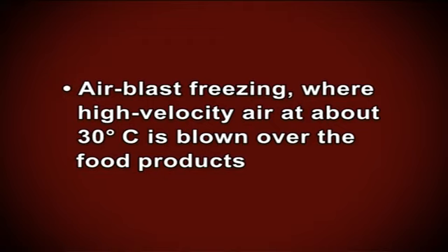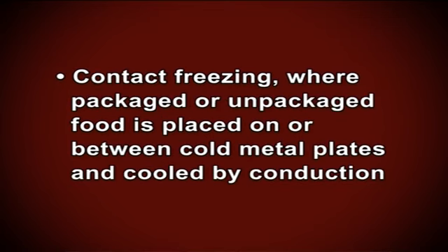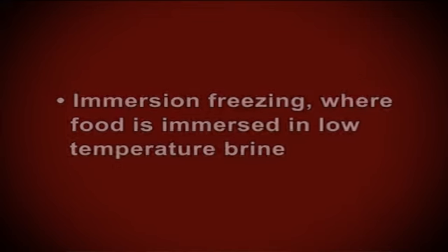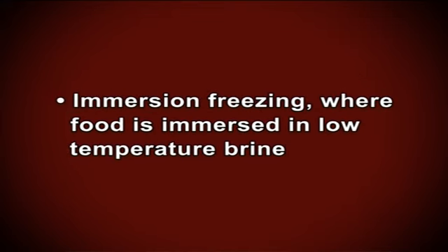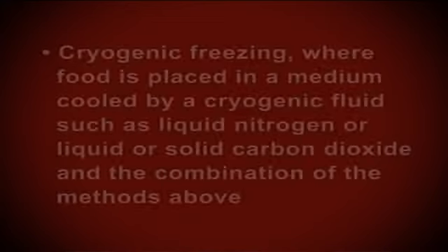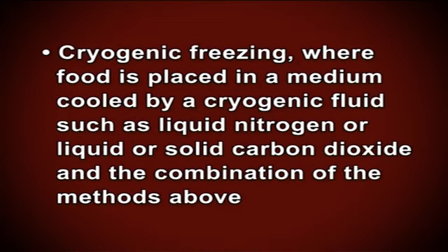Common freezing methods include air blast freezing, where high velocity air at about -30 degrees centigrade is blown over the food products; contact freezing, where packaged or unpackaged food is placed on or between cold metal plates and cooled by conduction; immersion freezing, where food is immersed in low temperature brine; cryogenic freezing, where food is placed in a medium cooled by a cryogenic fluid such as liquid nitrogen or liquid or solid carbon dioxide; and combinations of the methods above.